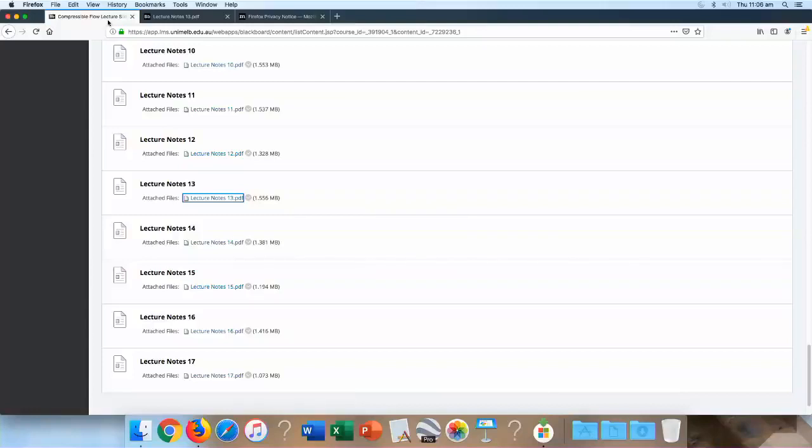So dm times the energy per unit mass is the amount of energy in a mass dm, and I'm simply going to sum all of that over the volume, and then look at the rate of change of that in the volume. And the rate of change of energy in the volume plus the net flux out of the volume. So that is H, if you include H, because you include the pressure work, H plus a half U squared times rho U dot N dS.